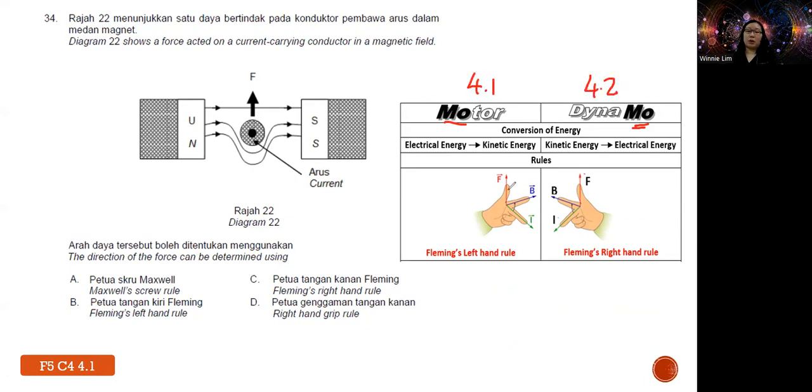So not to be confused, every time you see the circuit, if there is a power supply or power source, then you will use the left hand, that means Fleming's left hand rule. Like this one, current carrying conductor, I already mentioned, there is current. If in the whole circuit you don't see any power supply, and normally you will see a galvanometer based on the experiment setup, then you use Fleming's right hand rule. Hopefully you all will use the correct hand.